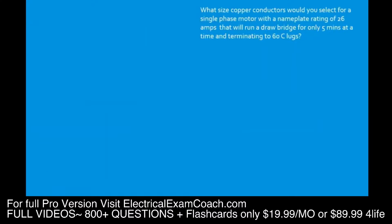All right, so let's look at our question again and answer it. In this case, we have a 26 amp draw. Remember, we don't use the FLCs on this type of question. You're going to use the nameplate rating. And we're going to have a drawbridge for 5 minutes. So we go to our table, 430.22(E), starting on the left-hand side, and let's look down until it says the word drawbridge. Right there in the middle section, it says drawbridges.